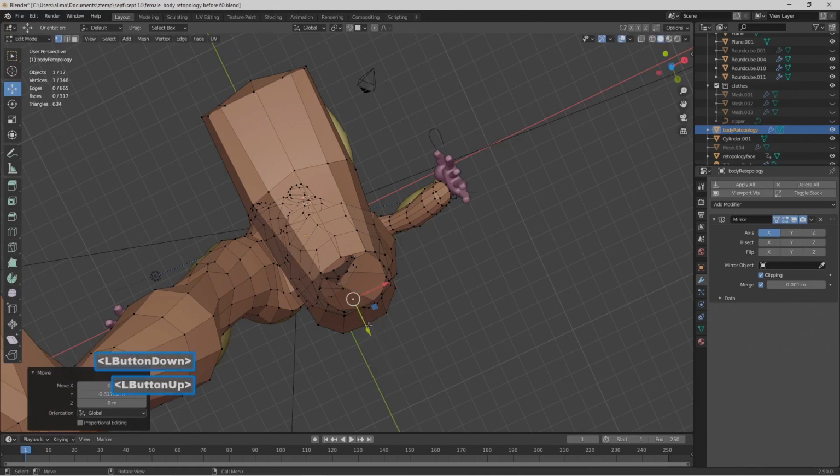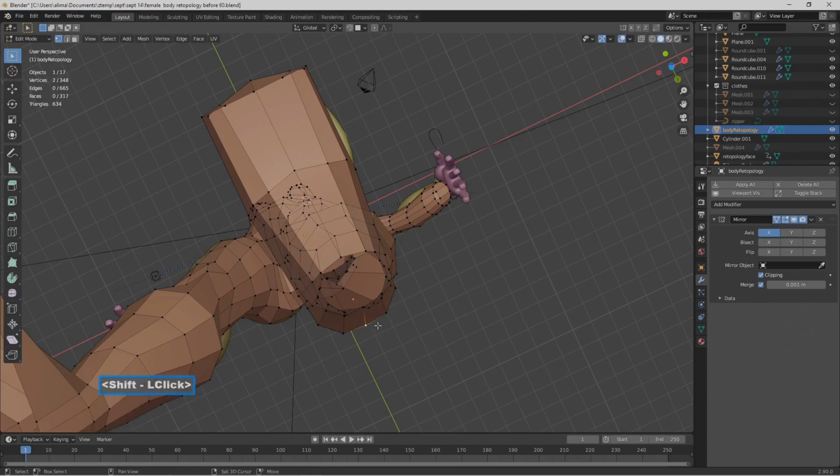Push that vertex out. I'm going to go to the select box in the upper left, mainly just to move the manipulator out of the way. I'm going to hold Shift to select here, as well as here, as well as here. There's 4 vertices there, so I'll press F to fill. Then I'll left click to deselect.